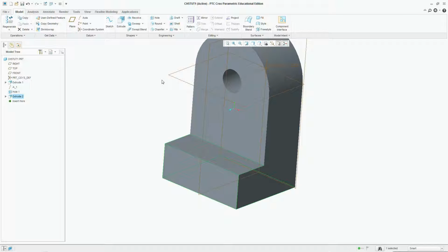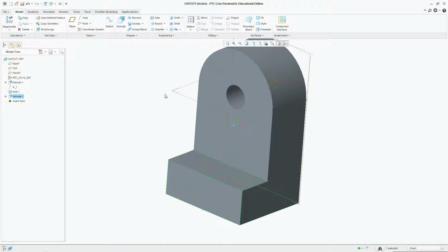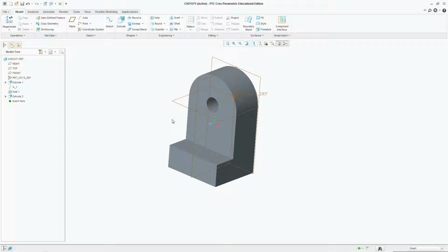And like I said, that's using a slightly different method than we've used before. We don't typically create the sketches from within the extrude command. The danger in doing that is if you make a mistake in the extrude command, then you have to redo the sketch every single time. The benefit to doing it that way is it doesn't have a whole bunch of sketches displayed over here in your browser, and it kind of cleans it up a little bit.